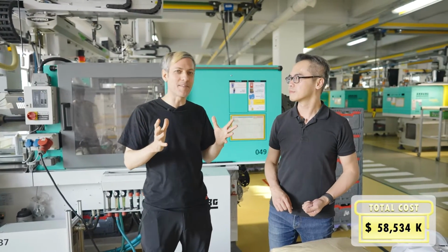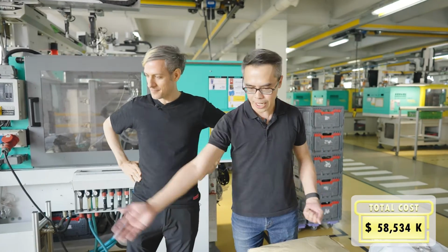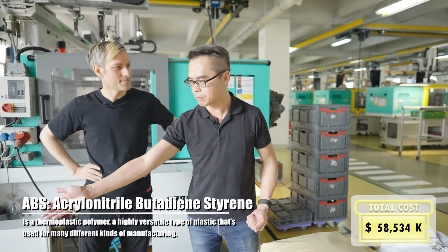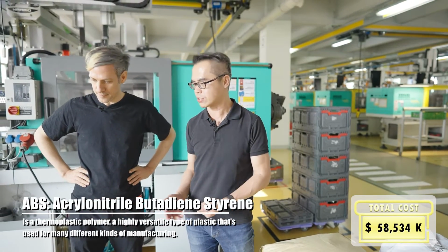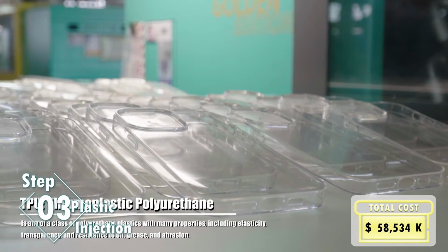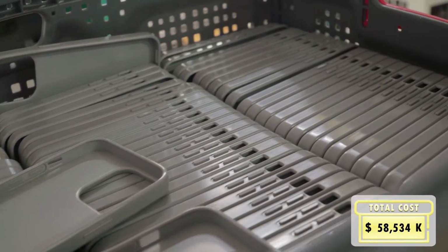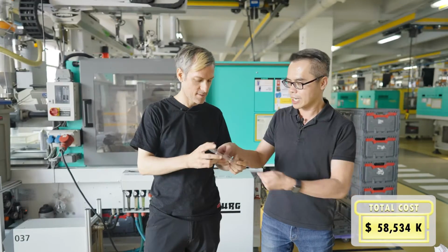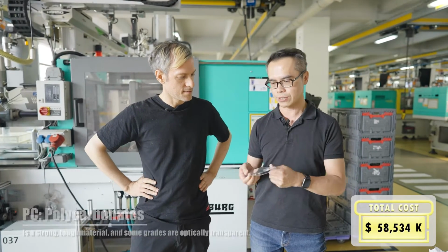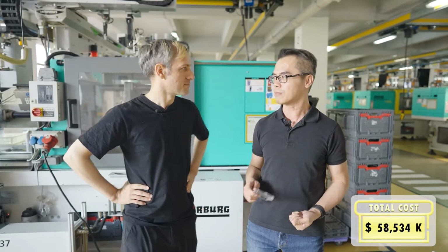Now that we've learned about the mold, we should talk about what we put inside the mold. Here we can see all kinds of different material. For example, this is ABS. ABS, the property is inexpensive and very strong. And this is the TPU. With TPU, we can make some soft products, so we have flexibility to make the touch better. In the bottom, this is the PC, and on the edge is the TPU. So we mix these two different materials together. So let's go see some more details.